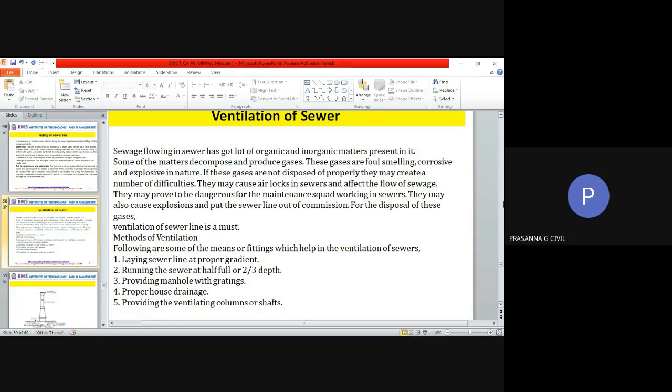You have various appurtenances in the drainage system to prevent backflow into your building, because otherwise you can imagine the wastewater from the main sewer outside is going to flow into your sewer pipe, and obviously it will start rising in your closets. Such conditions do happen in certain cases. Sometimes it is during heavy rains, where unexpected water enters the manhole and it's not able to take it up. Sometimes it is because of improper laying of the drainage pipe.